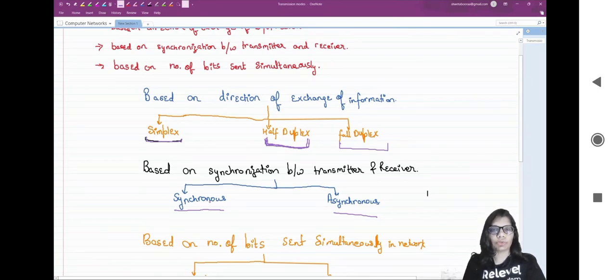Actually both the sender and receiver are placed at the same system clock, in which synchronization is achieved. And then in a synchronous mode of data transmission, bytes are transmitted as a block of a continuous stream of bits. Since there are no start or stop bits in the message block, it is the responsibility of the receiver to group all the bits correctly, and the receiver counts the bits as they arrive and groups them in 8-bit units, which is basically your byte.